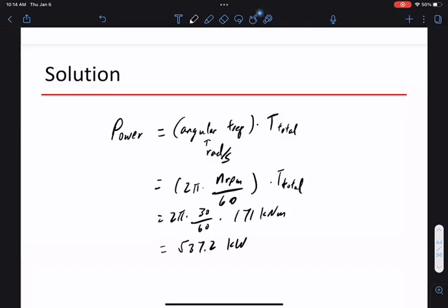Doesn't the increased number of blades lead to more turbulence on the path? Right. So one big factor is turbulence. Because once a blade sweeps through the air, there's actually some turbulence in the air. So if the next blade comes too close to it, because there's turbulence, you actually don't get that much power when you sweep through. Okay? So when you have multiple blades, you don't get that much power. So turbulence is a big factor.